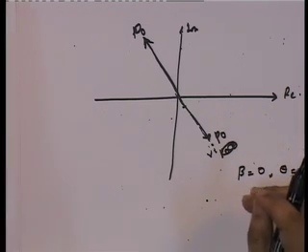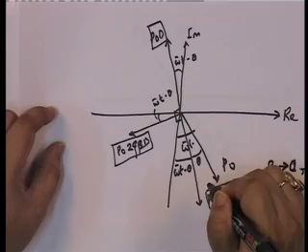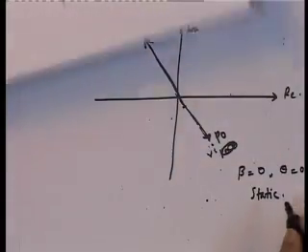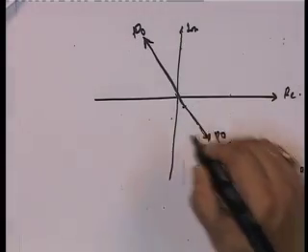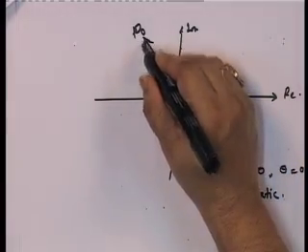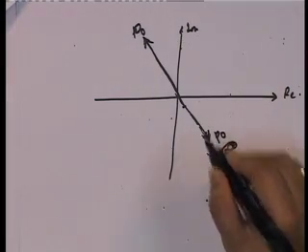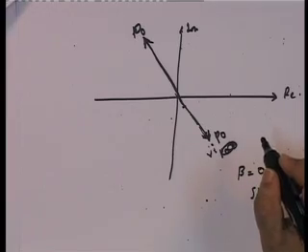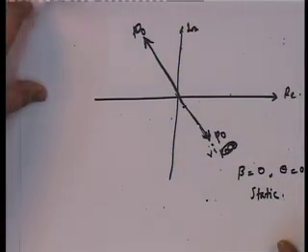So in other words, in the static case, this becomes the trivial solution where the equilibrating force, which is the elastic force, is P naught, the applied load is P naught, and the inertial force and damping force are 0. So that is the static case, very easy to understand.